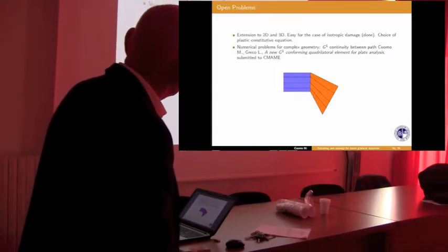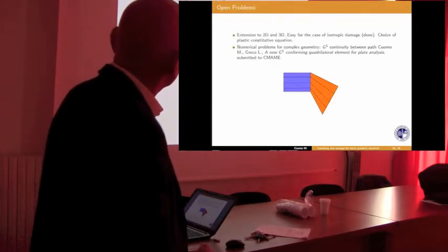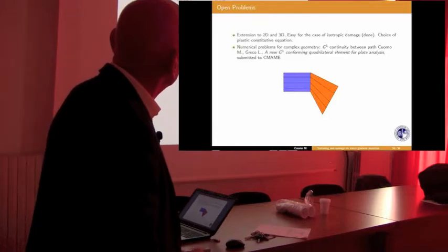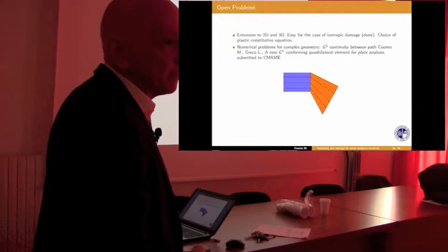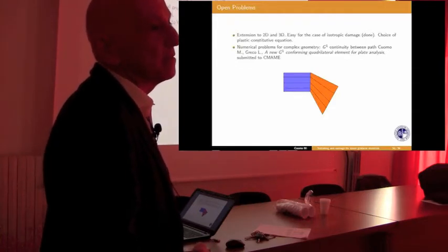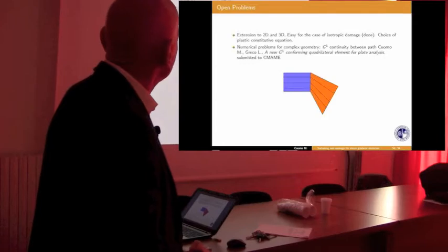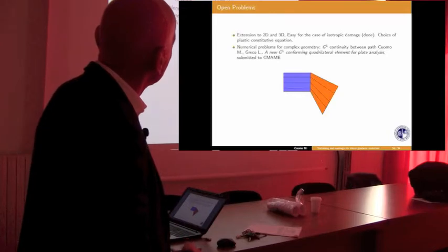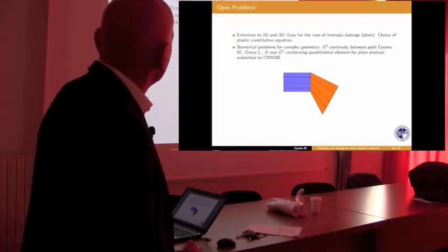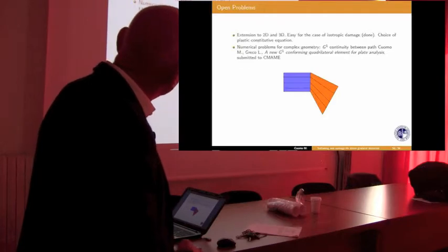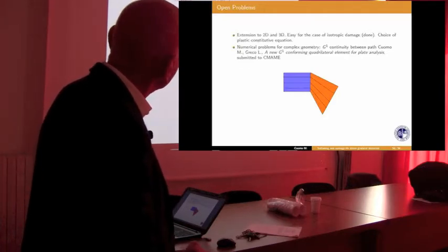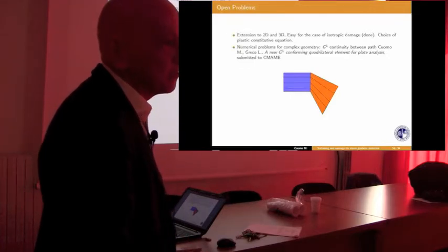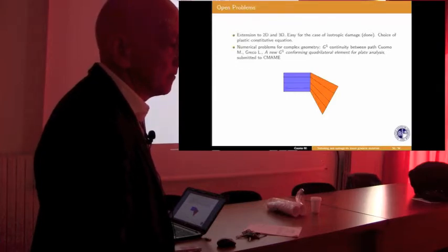There are problems we are working on now when you have complex geometry, because we need numerically G1 continuity between elements, or even with NURBS. We have G1 continuity within the patch but not on the boundary, where the parametric lines are not continuous. We have proposed a solution that we have submitted in a paper for plates, but we are working on this problem also with plane strain.